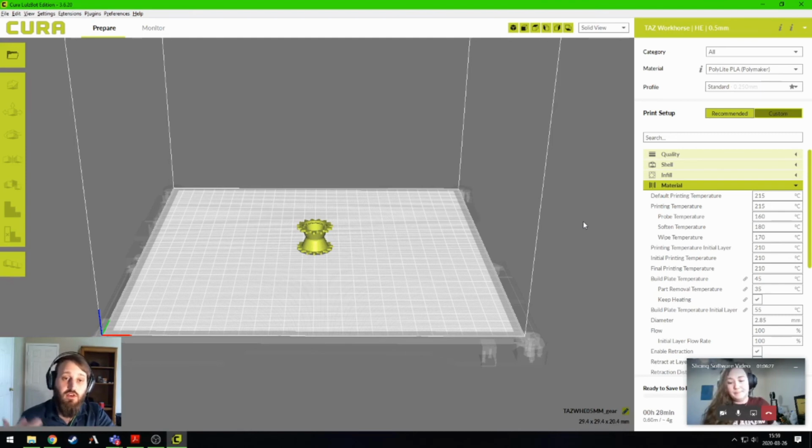Okay. So yeah, there's different manufacturers. Polylite is one that makes the 2.85 millimeter that we use with this Lulzbot because it requires a thicker piece of PLA, but most of your other PLAs, especially for at-home printers, a single nozzle, 1.75. Yeah. I remembered to commit that number to heart. So if you're purchasing at home, you'll have to keep that stuff in mind.